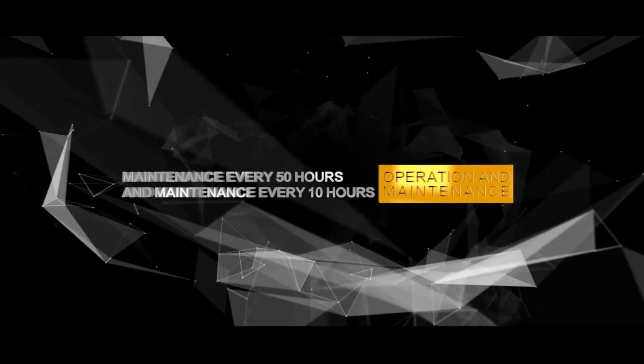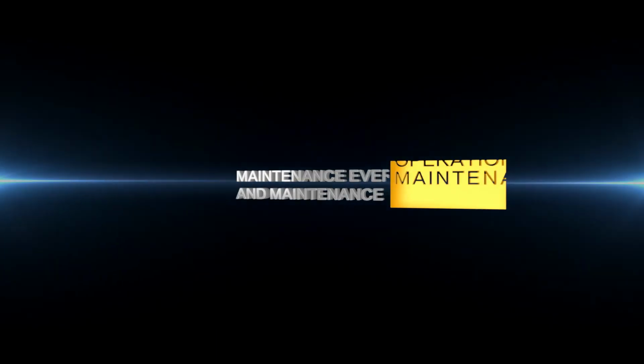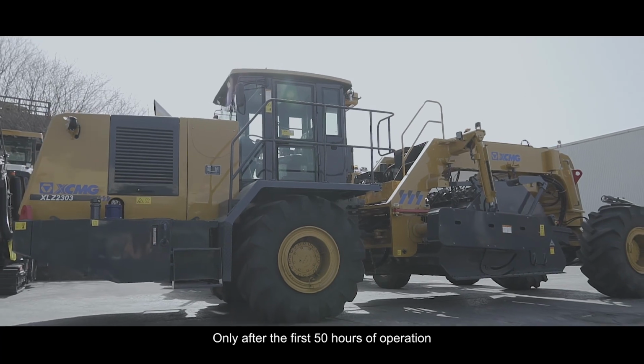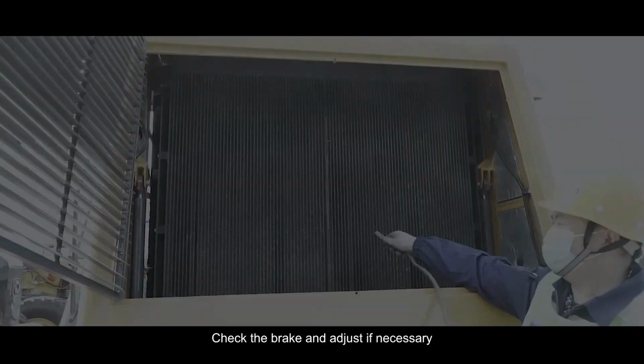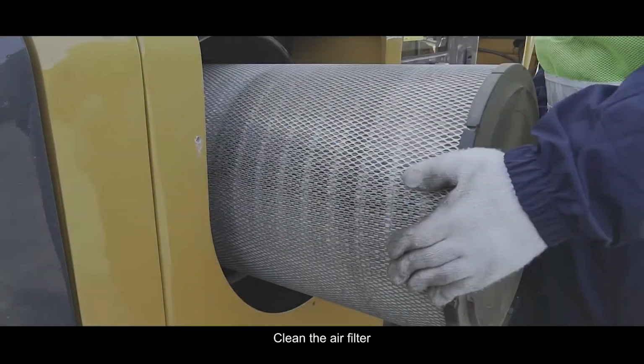Maintenance every 50 hours, together with maintenance every 10 hours. Only after the first 50 hours of operation will the following maintenance be carried out. Clean the radiator. Check the brake and adjust if necessary. Clean the air filter.